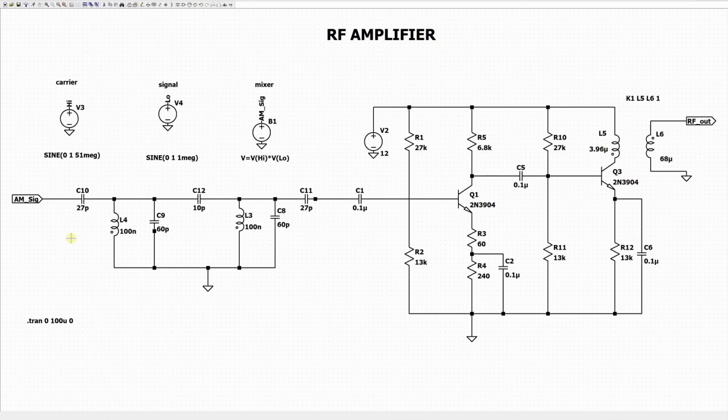I need to mention that we did not include the selective attenuator because that is a network of resistors, but we have this band pass filter which passes signals with frequency between 50 and 54 MHz. The output of this band pass filter is sent to the actual RF amplifier, which is a 2-stage amplifier, and this amplifier is supplied by a 12-volt battery,